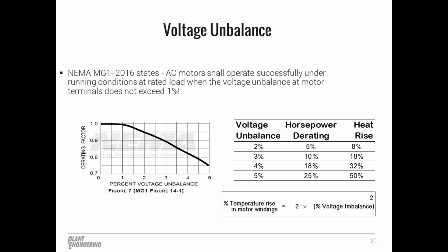But of course, voltage imbalance isn't the only thing that can cause some current imbalance. Unbalanced winding resistance could lead to it also. If you're measuring current imbalance with an ammeter out in the plant, with your motor loaded or unloaded, and you're seeing some current imbalance, de-energize your motor and then measure each phase-to-phase winding resistance so you can verify what that baseline resistance imbalance is.